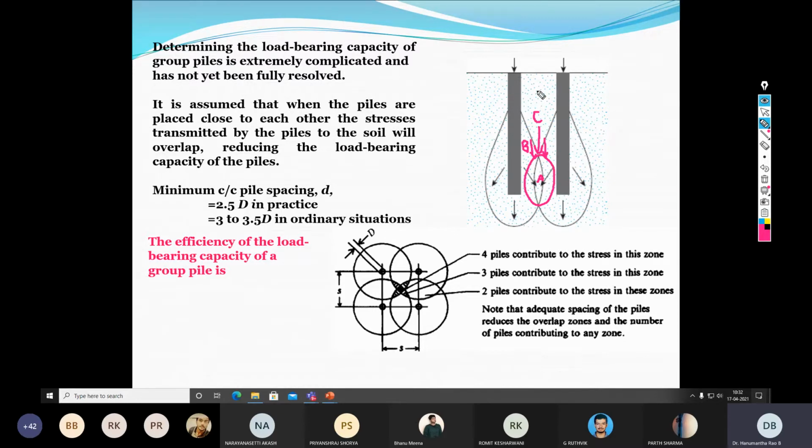Until there is a contrast in the material. For example, that contrast is possible between the pile cap and the soil. Suppose here, the above is the pile cap, below is the soil. So this zone C, right from below the pile tip, will try to settle again as a result of the settlement of zone A. Means within the due course of time, you can see a gap formation between the pile cap and the soil.